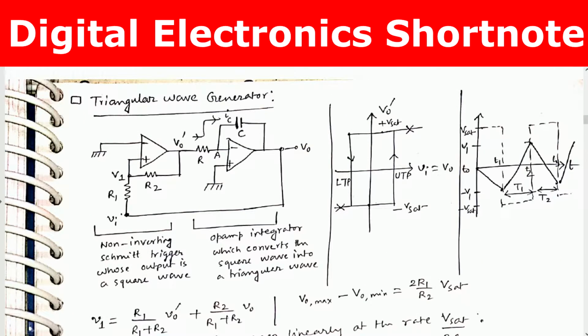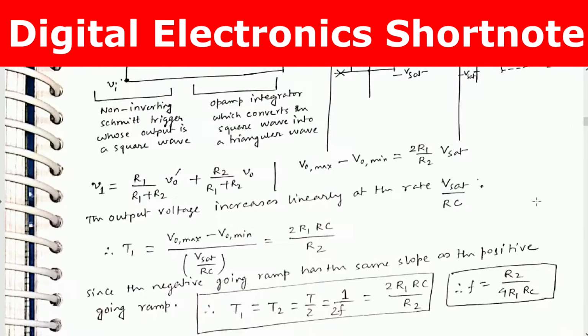Triangular wave generator. To do that, we are adding a non-inverting Schmitt trigger whose output is a square wave, then an op-amp integrator which converts the square wave into a triangular wave. So first we are producing a square wave, then we are integrating it, which produces a triangular wave. And these are some calculations, you can check them out.